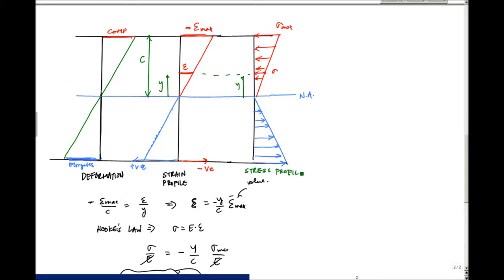Stress profile. Okay, and you'll also find later, if I calculate the force resultant here, I'll call that C, and then this force resultant of the tensile stress, this T, and the distance, this arm right here, and if I take moments about this point, I'm going to find that the applied moment, this Mz, whoa, let's put that back in.